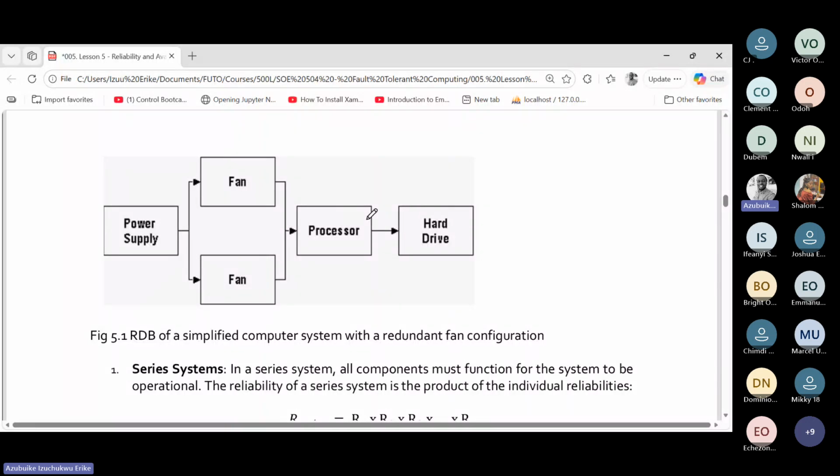So you see the radiator fan inside of your car, under your bonnet, usually attached to that place. If anything happens to your radiator fan and it is not blowing again, you will notice that the temperature on your dashboard will immediately rise. You don't want that, because if the temperature rises, the head gasket of your car is going to burn. But forgive me if you don't know much about cars.